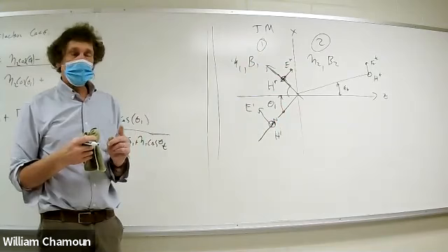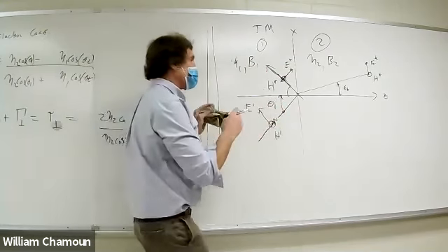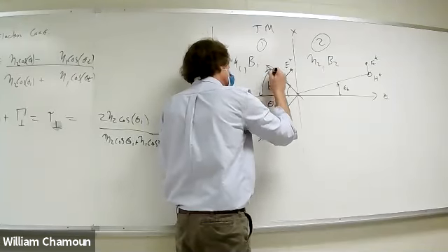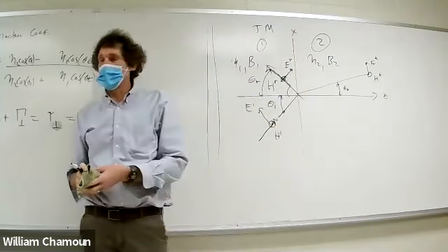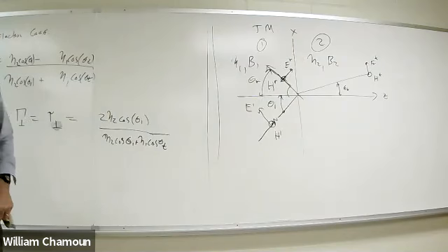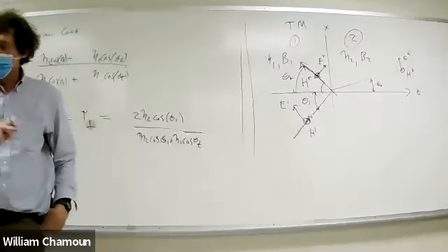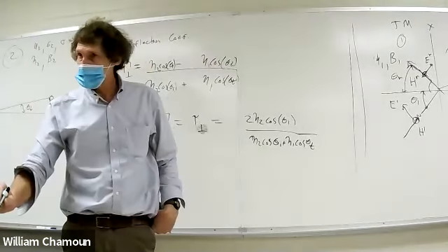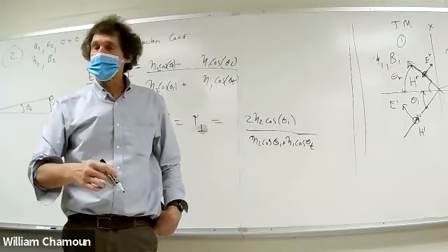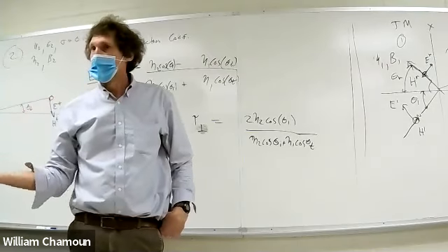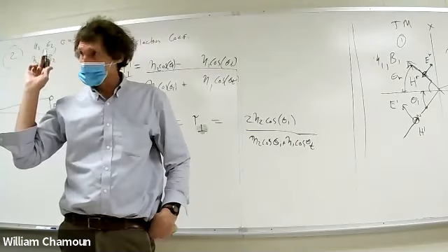Now, I'm going to make a comment here. I'll prove it, but the incident angle is the reflected angle here. It always will be, as long as these surfaces are planar. Mention one other thing, some of you may be looking on the internet. This is assuming you have mirror-like scattering, you have a perfect plane, the wave hits it, it's mirror-like, think of billiard balls on a pool table. The angle of incidence is the angle of reflection, without English and all that stuff. That's the way it always works with electromagnetics too. Assume the regions are mirror-like in a sense. Right?